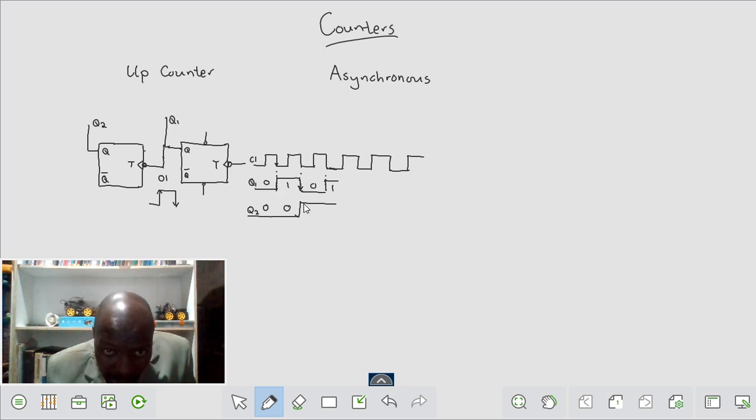But here now you can see that this would have toggled up, but now look here, this would toggle back down, and that's a trailing edge for the next one, meaning that this one will also toggle here. Remember that that one keeps toggling. It's a T-type. It will wait for another trailing edge before it can toggle back down.